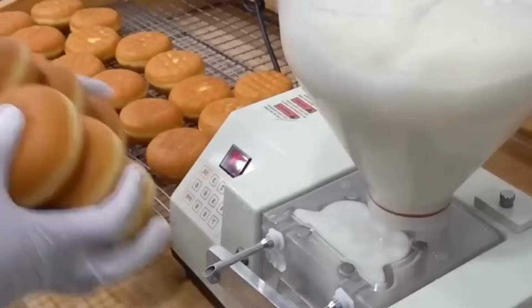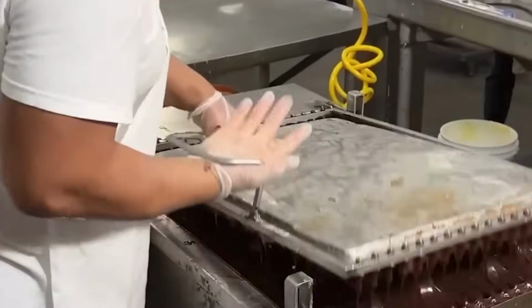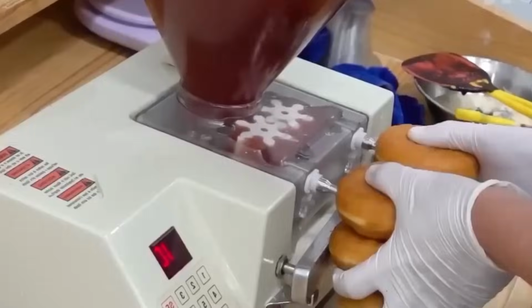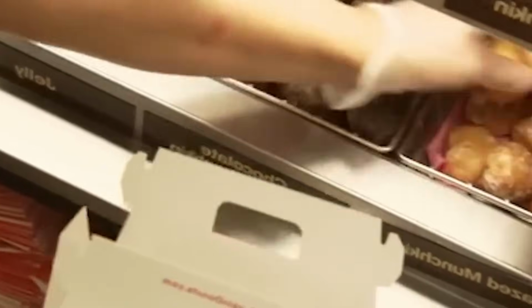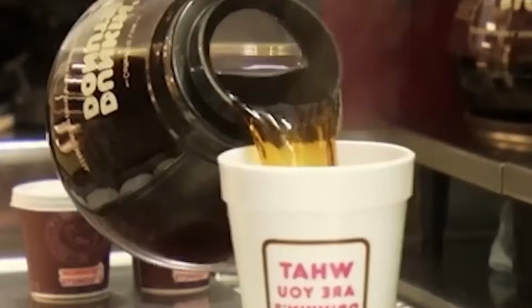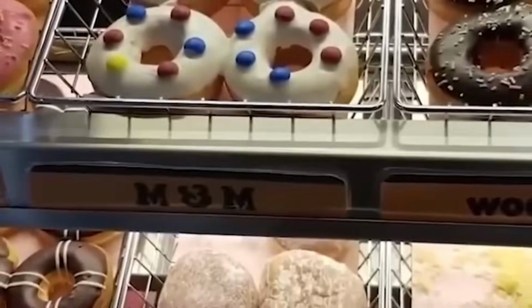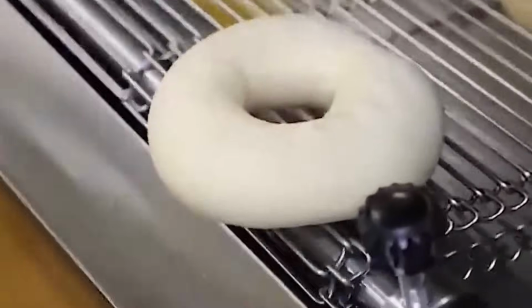Proofing conditions are held at 38 to 40 degrees Celsius, with 80-85% relative humidity for 35 to 45 minutes. Within the proofer, dough pieces rise and expand due to yeast activity. Conveyor motion is timed so that each tray spends the same duration in the chamber. Sensors track fermentation progression using size and weight benchmarks. After proofing, trays enter an automated unloading system that transfers the dough pieces onto a fryer in-feed belt.